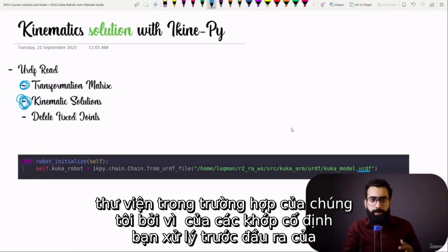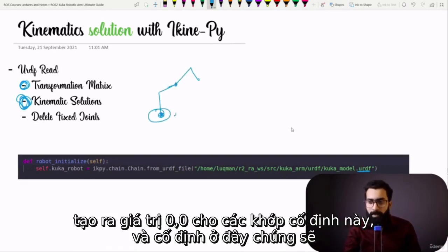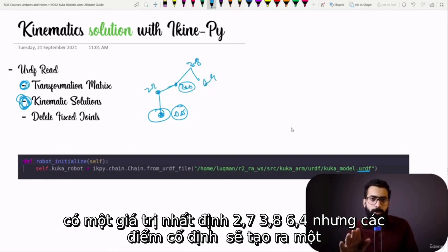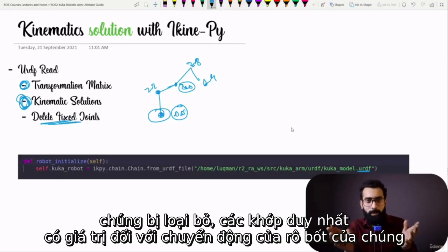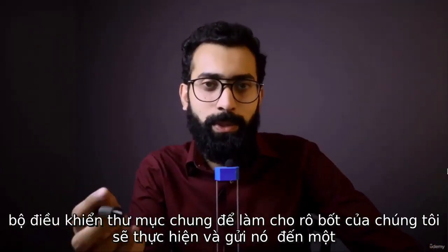In our case, because of the fixed joints in our robotic arm, we are going to face some problems. Fixed joint here and fixed joint here, they are going to be producing a 0.0 value. All other joints are going to have a certain value, 2.7, 3.8, 6.4, but the fixed joints are going to be producing a 0 value. We have to delete them with some Python programming skills. When they are removed, only joints which are valuable to the motion of the robot are going to stay there, and we will send it to a joint trajectory controller to make our robot move.